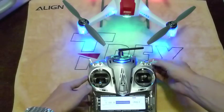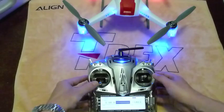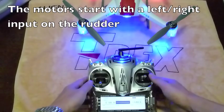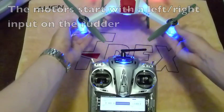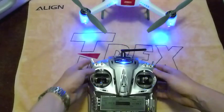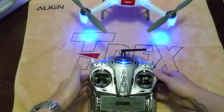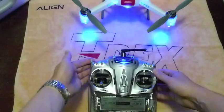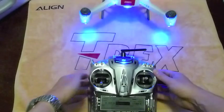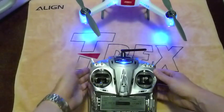What I'll do is I'll just put it into stability mode and just start the engines. So basically to start them, it's just a toggle left, right on the control. I'll just move this forward slightly. Okay, so I've still got the throttle hold on. As you can see, nothing starts. If I remove throttle hold, toggle left, right, the motors will now begin, and throttle hold to cut the motors.